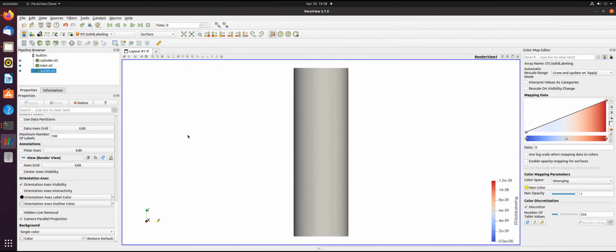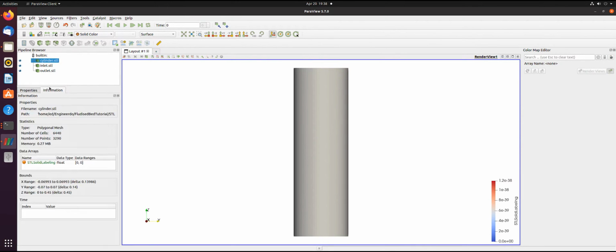One very important function of ParaView is that it can show the dimensions of the different meshes of my structure. This is important for fast modeling in the CFD as well as in the DEM. To see the dimensions, I select one part which is of interest. Here it is the cylinder, because I know that this is the largest object in every dimension of the coordinate system. If I go to the information tab, it shows me the number of cells and points. A lower number could be better for a faster meshing or DEM simulation.